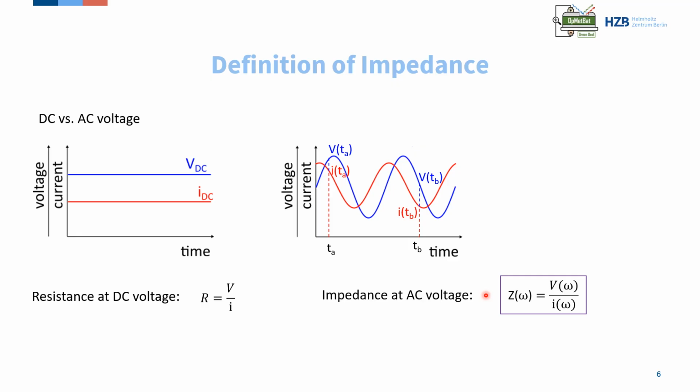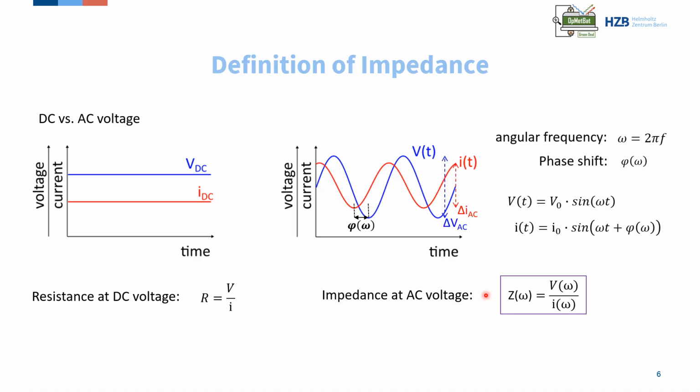Therefore, to measure impedance, an alternating sinusoidal signal, like voltage or current intensity, is applied, and then the response signal is measured to determine the impedance as a relationship between them. These oscillations in current and voltage have sinusoidal behavior of certain frequency and amplitude. Additionally, a certain delay between variations of current and voltage can also be present, so that the oscillations may differ by a phase shift.